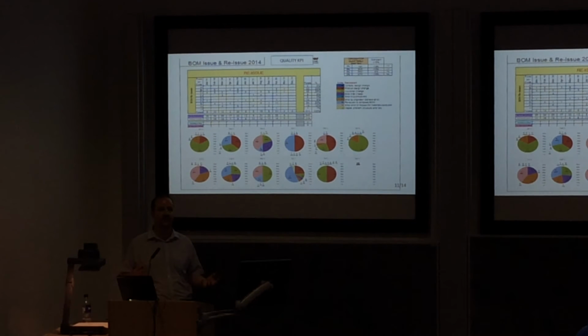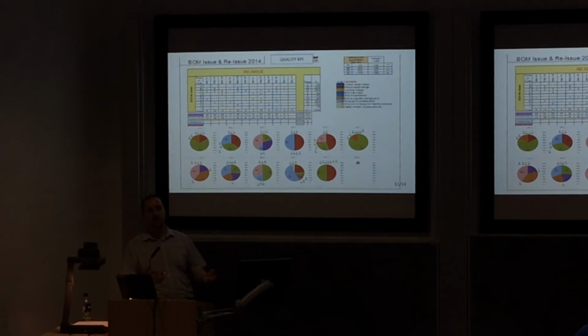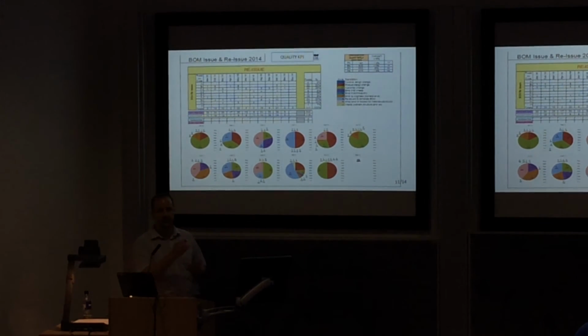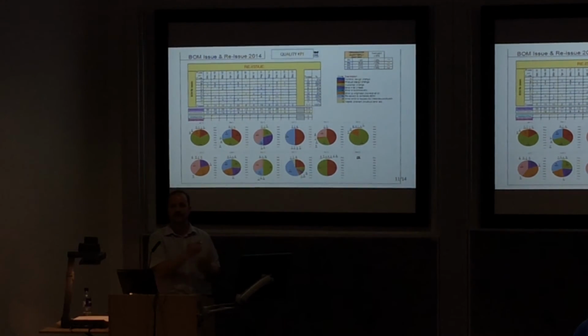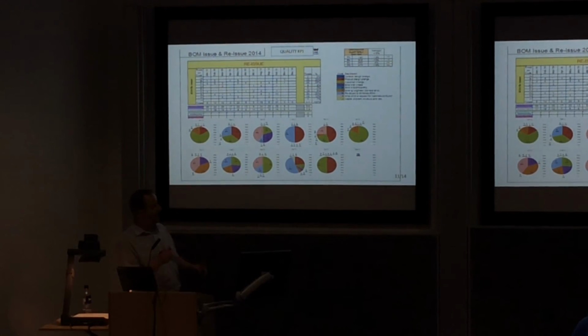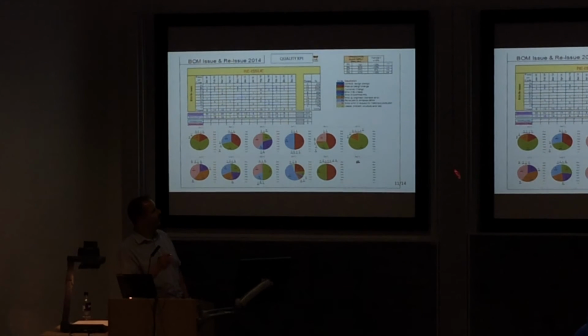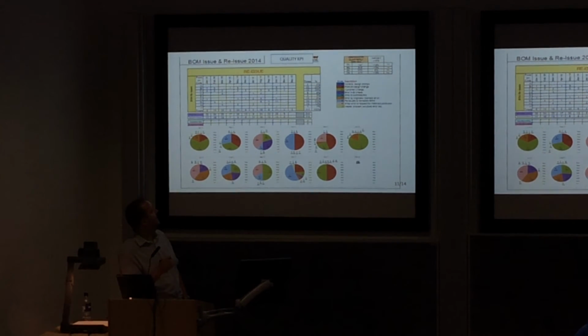We have very angry fitters coming up, or potentially making mistakes because they've used old copies of the documentation instead of the current copies. So I would keep track on a weekly basis, and also on a monthly basis, of how many times we would need to have changed our bill of materials after releasing it to the shop floor. I would also look at the reasons, because sometimes the reason is actually because our customer has changed what he has ordered.